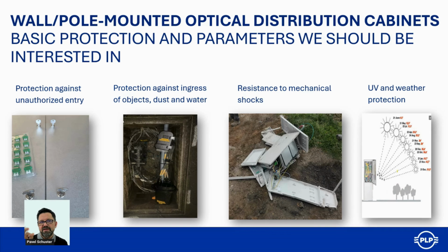And keep in mind, if you are purchasing a distribution point, enclosure or box which should be placed outside, don't purchase it when it is made of ABS material, because then the lifetime in the sun is much shorter than other materials like PC-ABS or the mentioned polycarbonate.